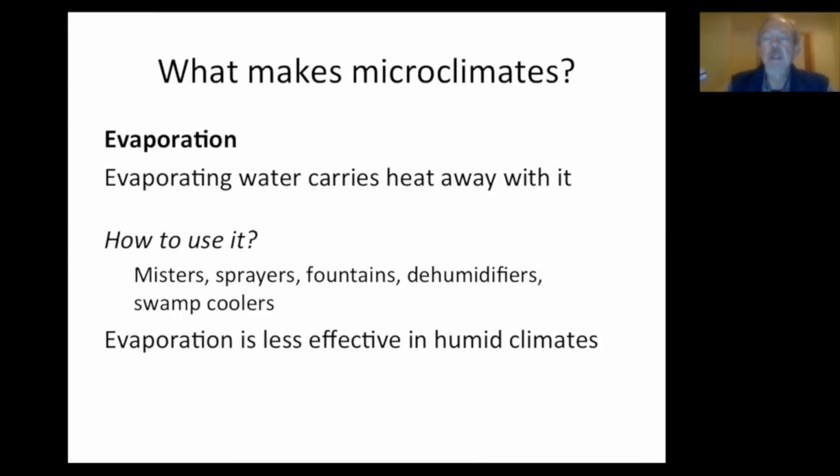You put a fan behind a moist curtain or a mossy wall or something like that. And at least in a dry climate, swamp coolers are a way of really cooling things off nicely, because as the warm, dry air blows through this wet thing that's inside a ventilated box, is essentially what it is, it cools the air off, and those really work.